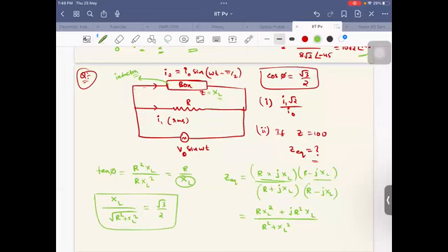But in the question, what they're asking is the maximum of I1 root 2 by I naught. I naught can be written as what? The peak is V naught by Z of this one. I naught is in the denominator, so that means V naught by XL.